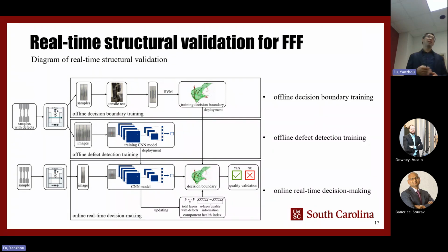So compared with the previous method, this method can infer the defect impact and then conclude how the defect impact influences the final product quality. Based on the defect impact decision boundary, the system can make the right decision to continue or to cancel the printing.